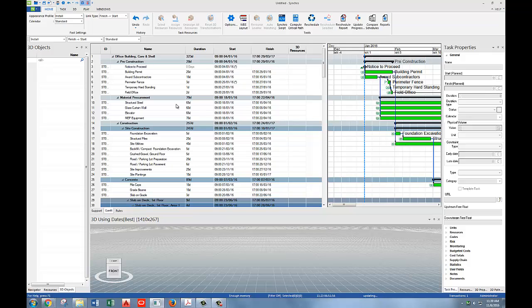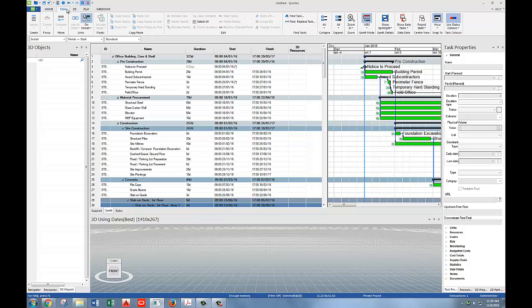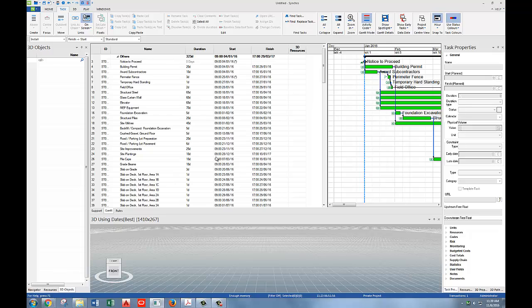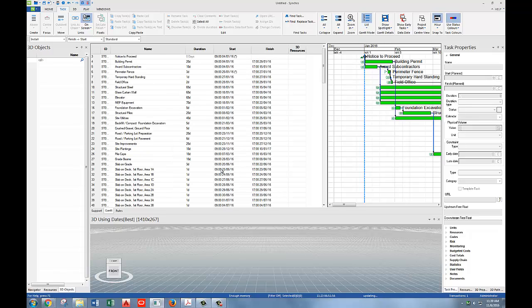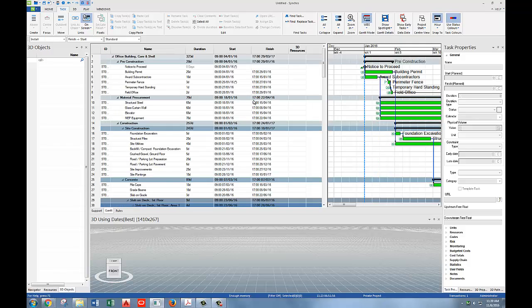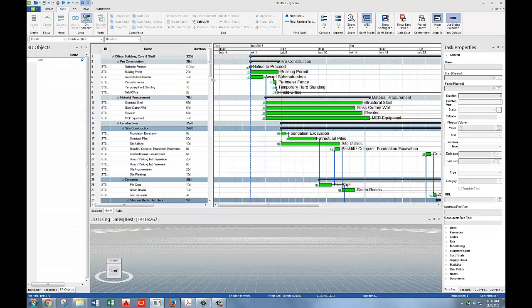And in terms of how you view your task list, up here at the top, if you go to the task and go over to Gantt mode, you can see that currently you should be displaying by work breakdown structure because that's how the schedule is built. If you want to view it by activity code, click on activity code. Likewise, if you just want a list version, click on the list. For now, we're going to leave it in the WBS. And there's one more little thing that I want to talk about over here in the Gantt window.